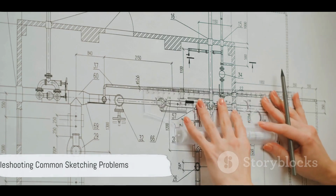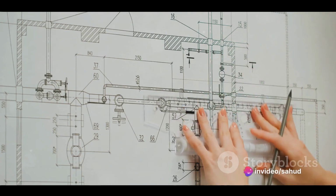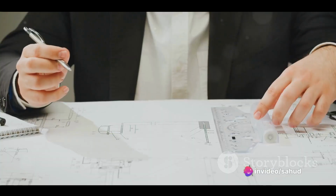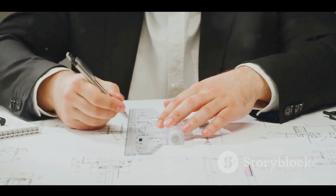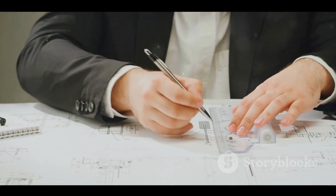Even the best designers run into problems. Here's how to troubleshoot common sketching issues. Let's start with one of the most common issues: being unable to complete a sketch. This typically happens when your sketch isn't fully defined, meaning it lacks the necessary constraints or dimensions.